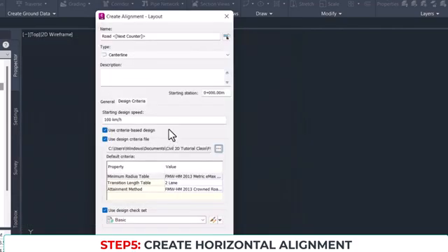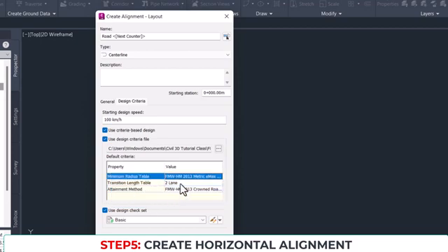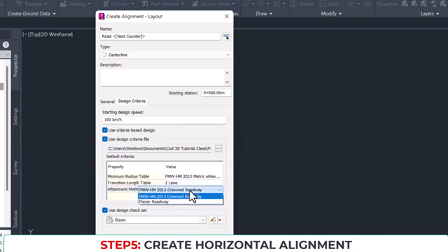Once I open that up, you would see everything is customized to Federal Ministry of Works, Highway Manual 2013. So you can see now based on our design, we have a maximum super elevation of 6%, and the transition lane is 2 lanes. The attainment method is crowned, so it's a crown road. You know what crown means? We're having a cross slope. The road has a camber.